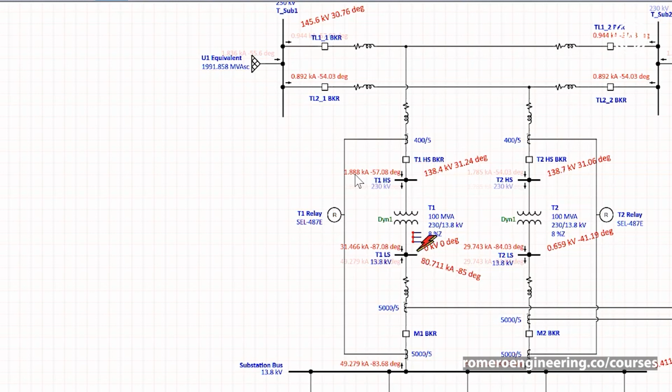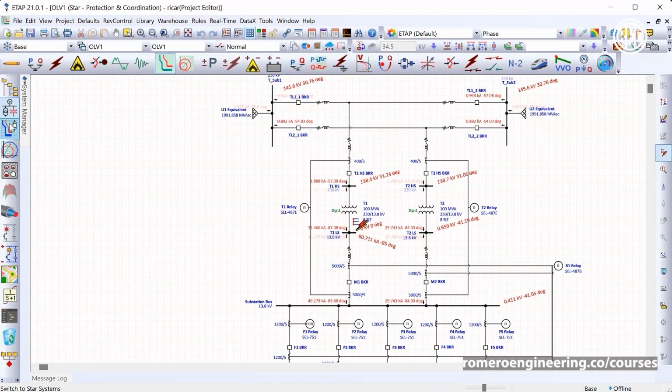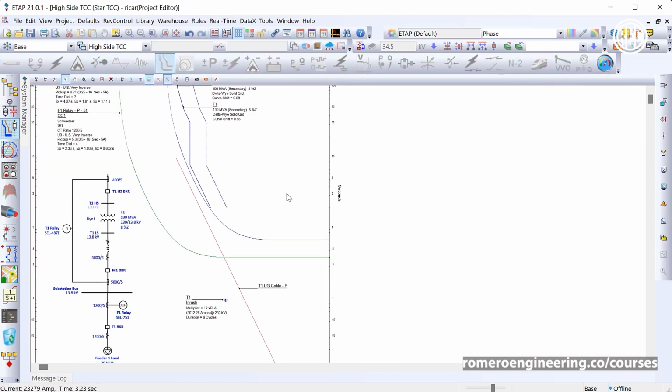1,888 amps. And what I'm going to do for my example is set my phase instantaneous overcurrent element just above that number, which again is going to guarantee us that we never trip for a fault outside of the transformer or further down from the transformer. All right, so we have that number, 1,888 amps. Now going back over here, we also need to consider the inrush current.